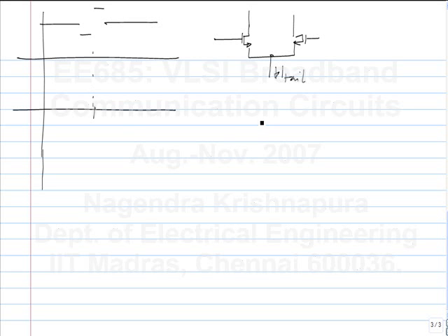output is simply a scaled version of the current, right? The output current of the differential pair depends on I tail. So, and that goes into some fixed resistor, so the voltage also is directly proportional to I tail, you can say. I mean, there is some nonlinearity involved, but the swings are directly proportional to I tail. So, for the ideal value of current, perhaps the output would look like this.